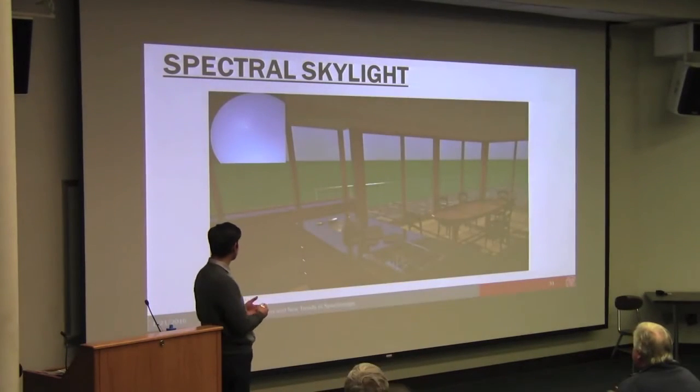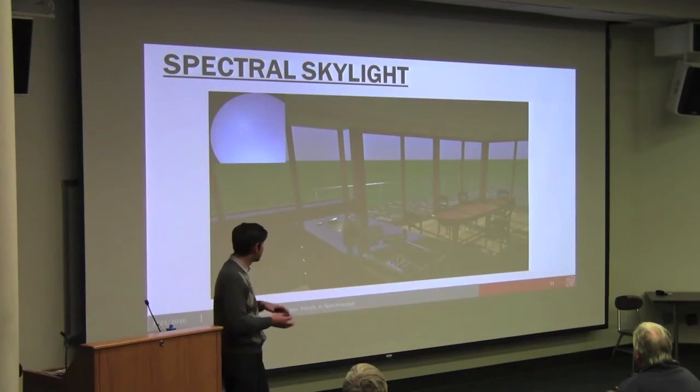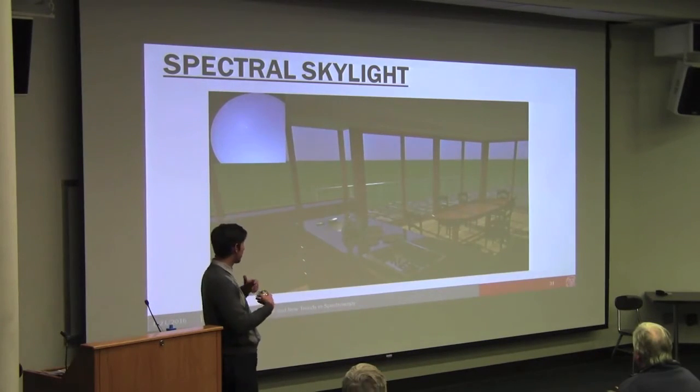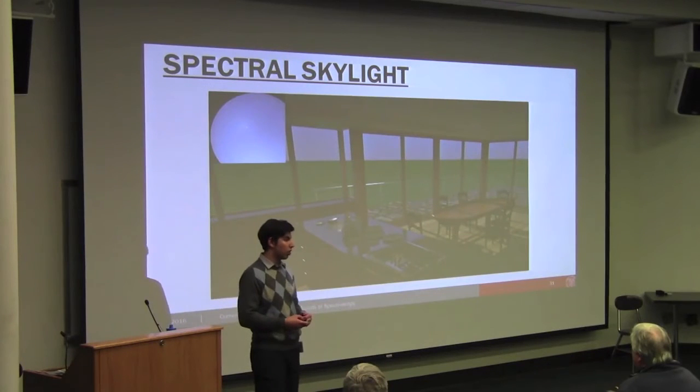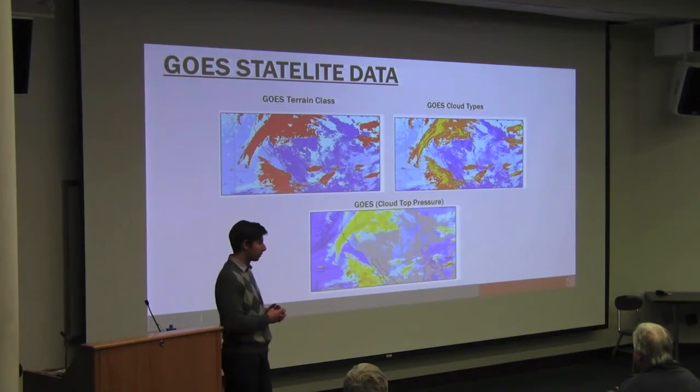and then use that sky to have a daylighting model for a kitchen scene. I'm an engineer, so this isn't going to be as pretty as some of the architectural scenes. But it's pretty close to the kitchen we had before, where I can do these harsh skylights and everything, and it's doing both a thermal model and a daylighting model all together. If I measure any point, I can validate that it's actually working as well.